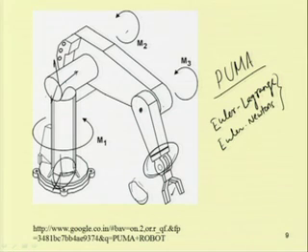To find what torque is required at this joint, that means we are putting a motor at this joint, and also at the other joints we are putting different motors. At the joints we are required to find what torque is needed to manipulate this robot. To find this torque, we have to write the dynamic equation of motion. By finding this dynamic equation of motion, one can obtain the response of the system.